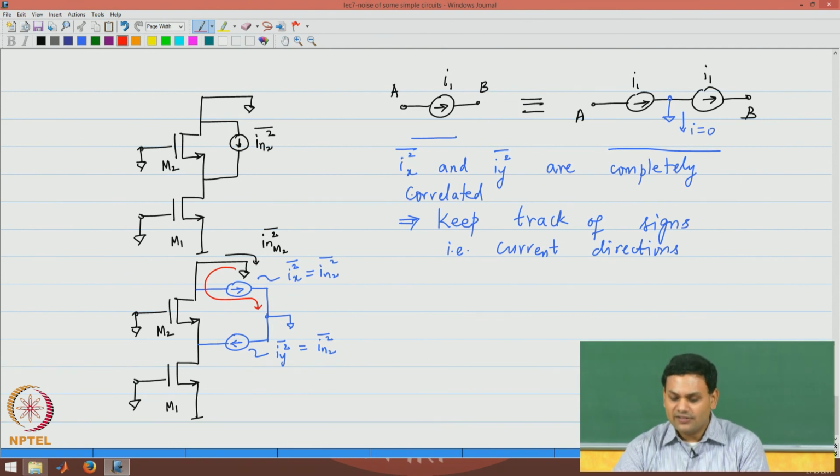In other words, the current source Ix has the option of flowing back into M2 or flowing into the short circuit. Since current always takes the least resistance path, all of Ix will flow into the output short circuit.